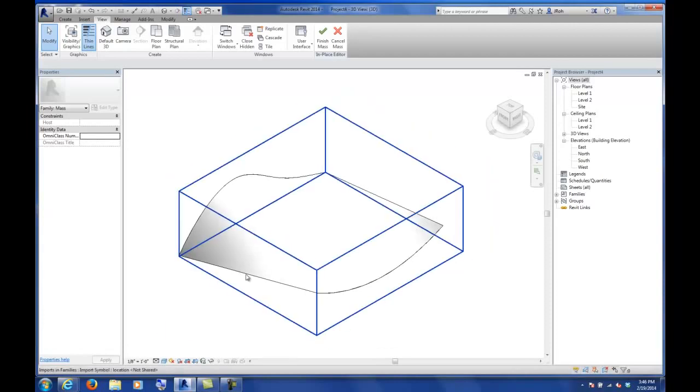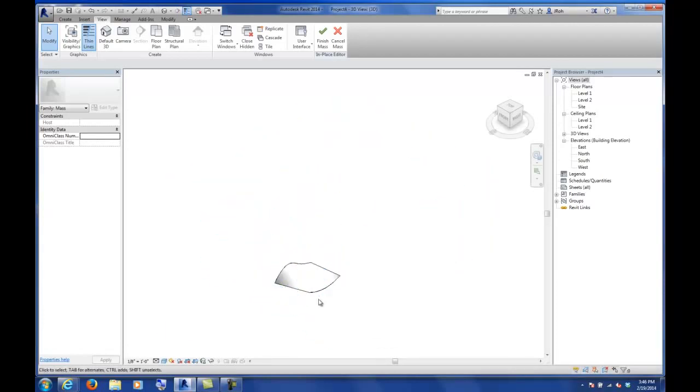I basically just have this NURB paper form. And when I was modeling this in Rhino, I was in inches. So I actually need to scale this up. If you're going to be bringing things in from other files, Revit's global unit is the foot. So you want to make sure that all your Rhino files are already in feet and inches units instead of working just in inches.